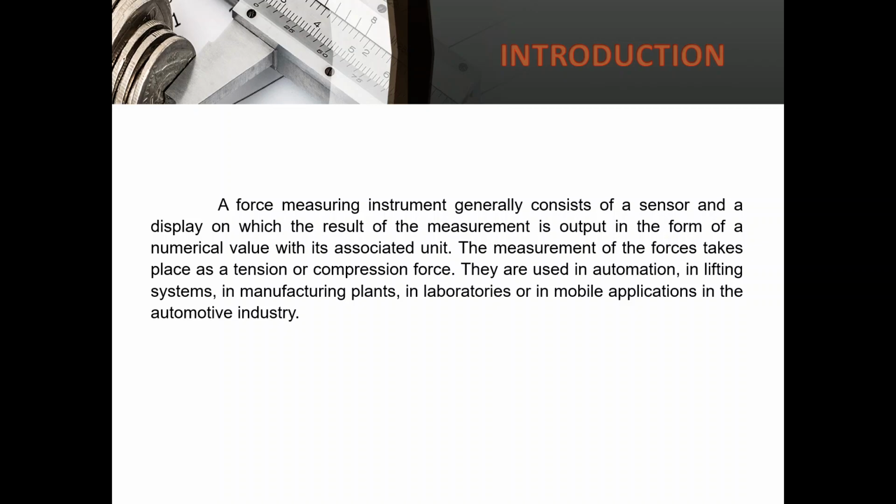For the linear motion of particles or rigid bodies, only the direction and force magnitude is important. However, the point of application is critical if you also put consideration in the angular motion. Furthermore, although the concept of force vector leads one to consider a point of application, in reality, direct contact spread over a finite area rather than a single point is generating more external forces. This introduced the concept of pressure, that is, force distributed over an area of contact.